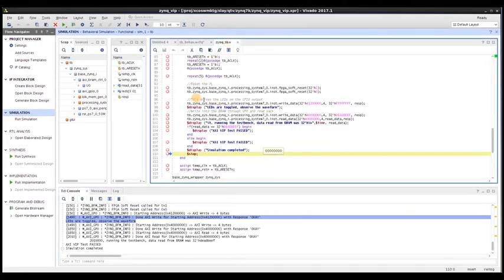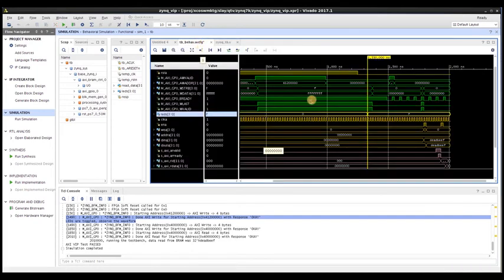By looking at the Zynq test bench, you can see the specific commands used to drive the transactions. As you can see by the example code, a write to the GPIO is being performed that results in the LEDs being driven to on. The waveform shown here highlights this transaction.